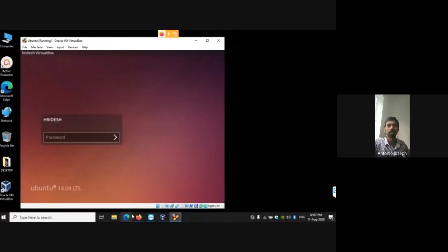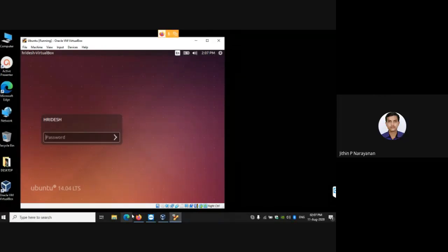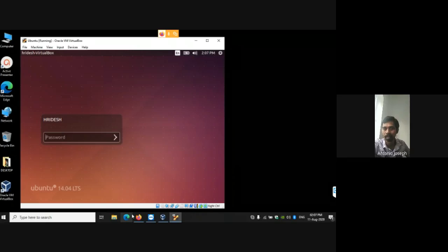Suppose in the x direction it is 20 centimeter. What about y and z? It is 10, 10. In y and z, if we are giving the grading as 3, that means the first element in the y direction and z direction, you are dividing into different elements that you will be specifying in the second command of that particular line.